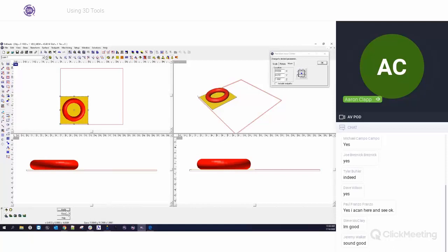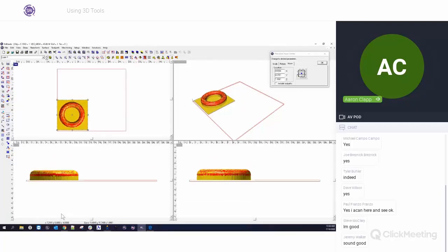I'm going to hit apply. Once I hit apply, you'll see it process there for a second, and it doesn't look like it's done anything. Just hit close, and then you're going to get this funny view here. Basically, what we're seeing is the mesh and the relief are sharing the same space, and so some of the colors are coming through. So I'm just going to deselect everything, click on the center object, and then move one of them out of the way.